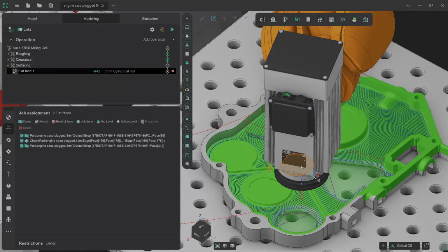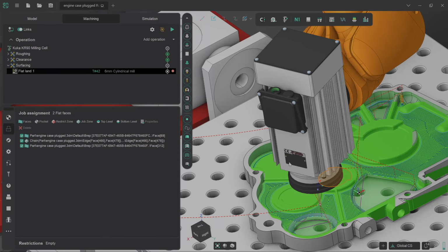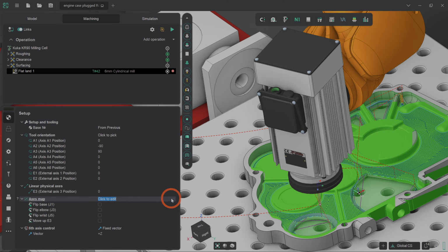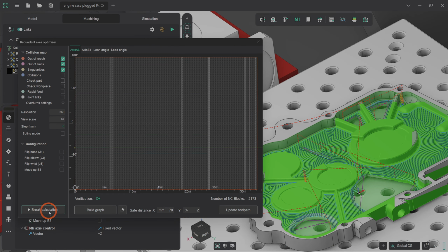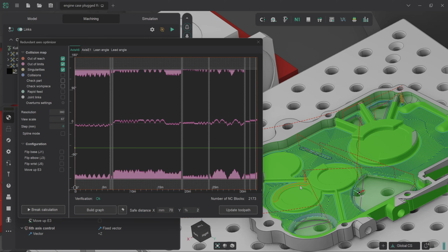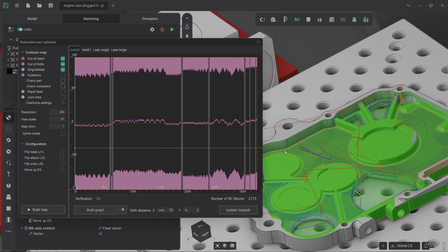Excellent. So we've got everything flattened out here, and that should be good. I'm going to leave the other sections for a secondary operation just to be safe, but for the moment I'll just quickly double check the axis map since we have extended that toolpath quite significantly at this point. I don't think there's going to be any serious problems there. And of course, we've extended this toolpath section, but we've removed all of the exterior ones, which is why this graph is now exceeding the bounds.